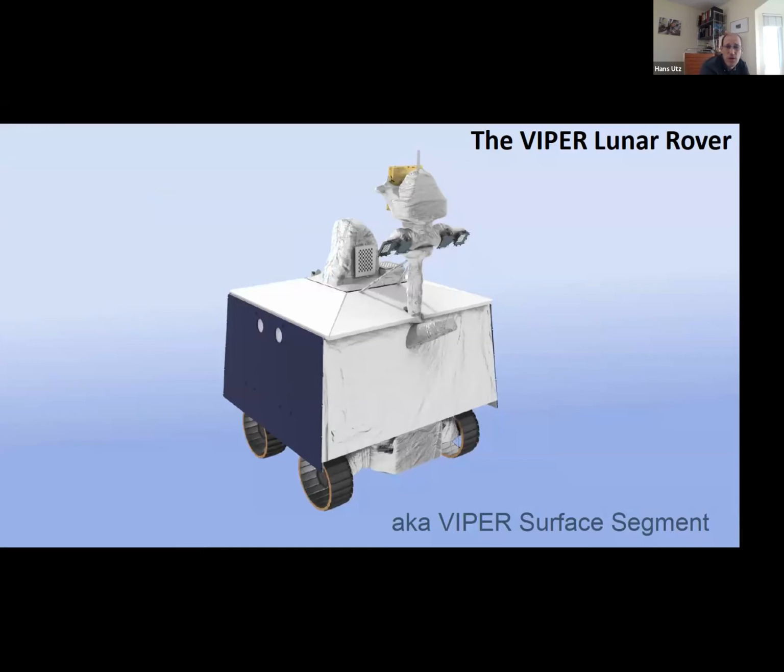And this is the rover that was designed to do this job. The solar panels are mounted on the sides due to the low sun angle on the horizon, and a radiator is on top. It has a four-wheel drive system with an active suspension. It has a mast with a stereo camera pair and lights, as well as a directional antenna for communication back to Earth. The science instruments are three spectrometers and a drill, of which you see here the drill tower in the middle of the rover.